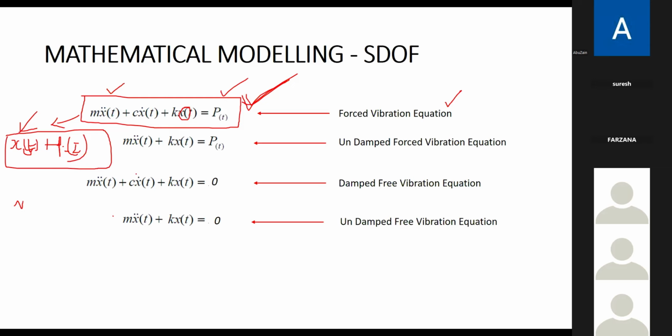They do this procedure below, but finally they take the decision based upon this forced vibration analysis. Now in the forced vibration analysis, because of damping, some force is taken. So from a conservative point of view, because modeling damping is very difficult, they go for global damping. Local level modeling of damping is very difficult in numerical modeling. For example, the column reinforcement is different in different locations, so obviously the damping behavior is different. If you go to the element level, we can model it as a global damping.